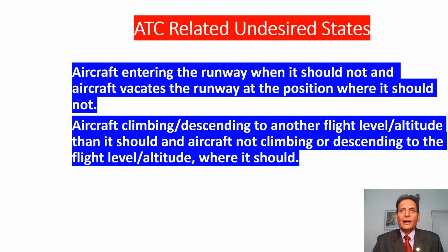ATC related undesired states: aircraft entering the runway when it should not, and aircraft vacating the runway at a position where it should not. Aircraft climbing or descending to another flight level or altitude than it should, and aircraft not climbing or descending to the flight level or altitude where it should.